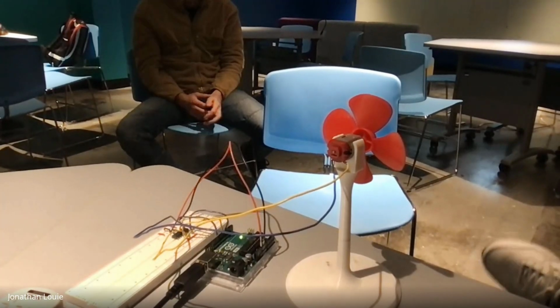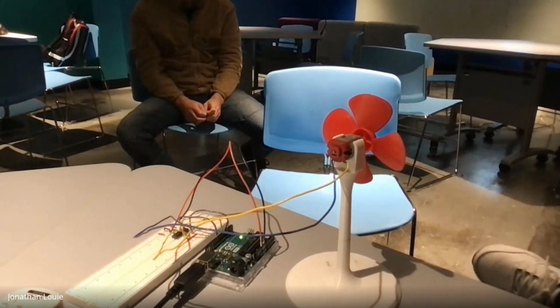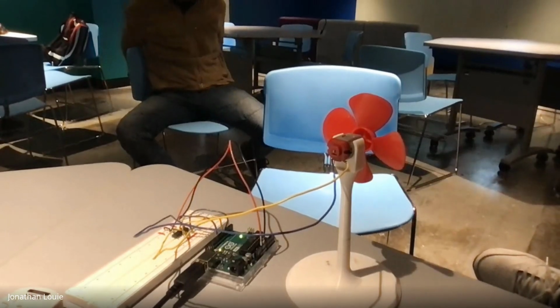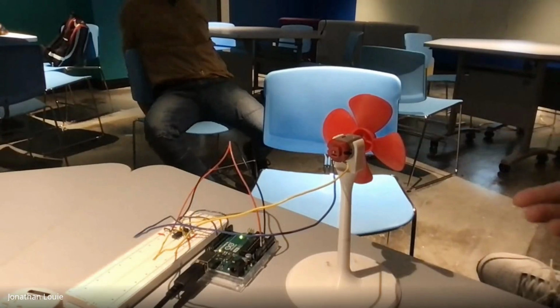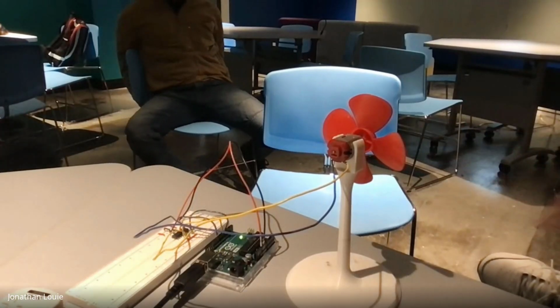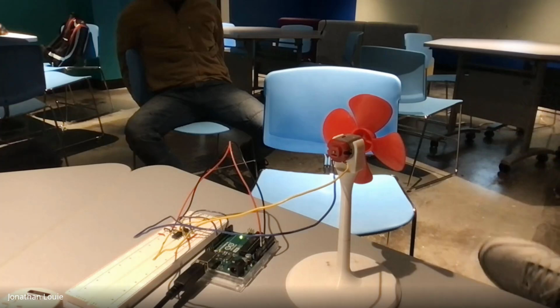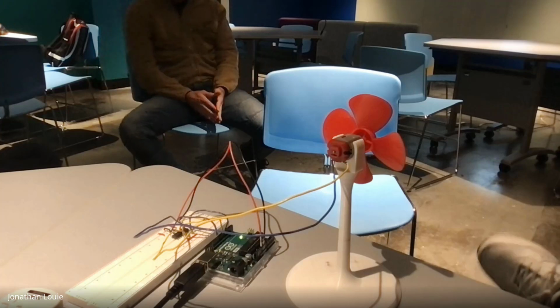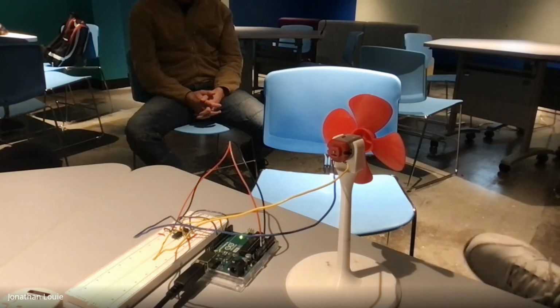Is it better to have those peripherals on the actual board itself, or separate? I noticed that the LED is built into the PCB here, but not this fan, obviously. What are the trade-offs there? Right. So the main trade-off is that once something's physically integrated into that board, it's more difficult to replace it as an individual component. Hypothetically, if this were an actual product, you'd probably still want the fan separate, because the failure rates for your fans are likely different from the electronics.